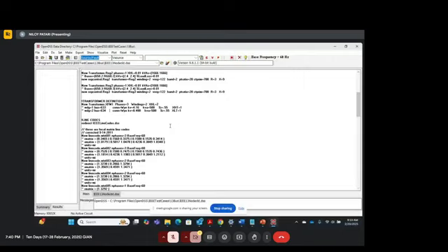But when you have to transfer that power to houses, at that point you have to put a service transformer on the pole top, it can be pole mounted or wherever it is. Then you bring that high voltage down to 480 volts or 240 volts. Generally it's a center tap transformer. I'm not going into much detail, but from that transformer onwards, whatever connections you have to each of the houses or residential customers, that is known as the secondary side of a distribution feeder.